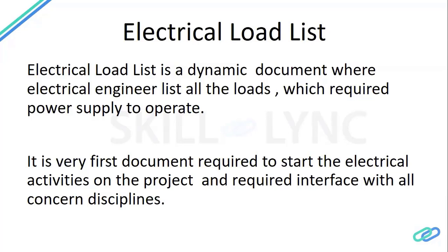Initially you have very tentative loads, but then you calculate and get inputs from manufacturers and motor vendors, and then you have the final inputs. That's why this document keeps changing throughout the project cycle, and that's why I'm calling it a dynamic document. It is the very first document required to start the electrical activities on the project, and it requires interface with all the concerned disciplines. Focus on this part: the required interface with all the concerned disciplines.